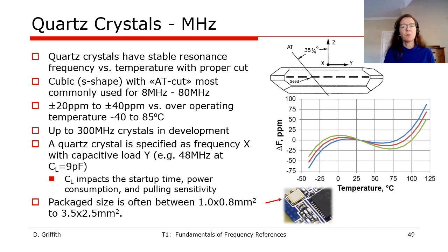Finally, crystals have to be packaged to be used together with an integrated circuit. The quartz crystal package size is fairly large given that it's a single passive component, with sizes between 1 by 0.8 millimeters and 3.5 by 2.5 millimeters being the most commonly used ones today.